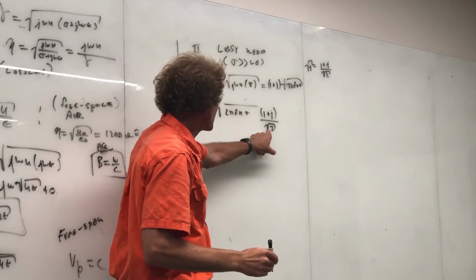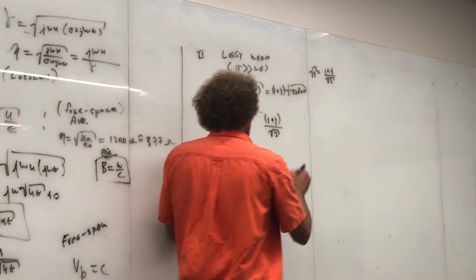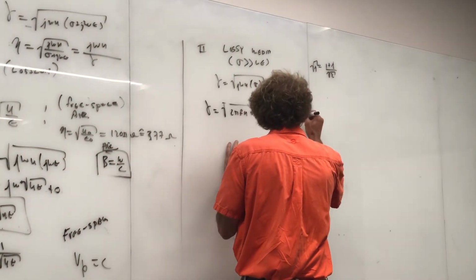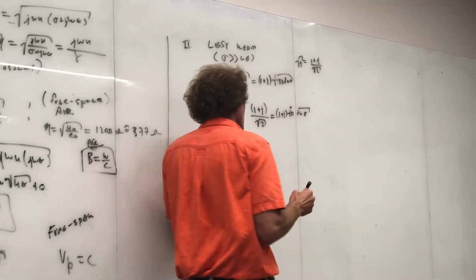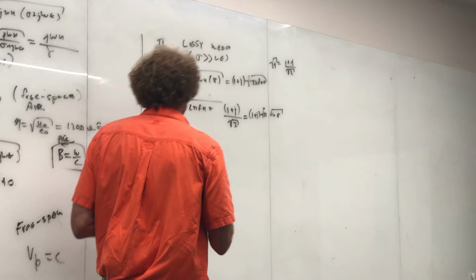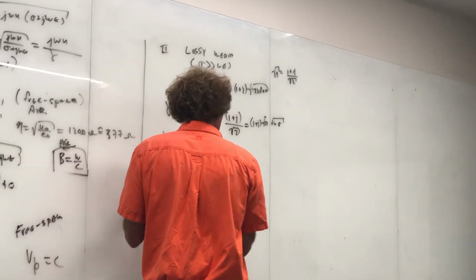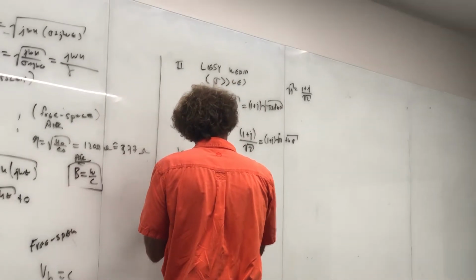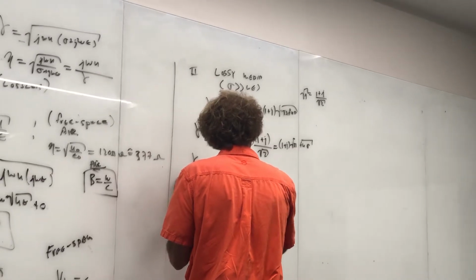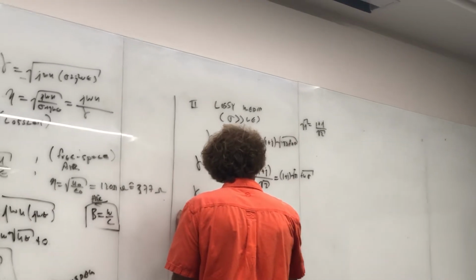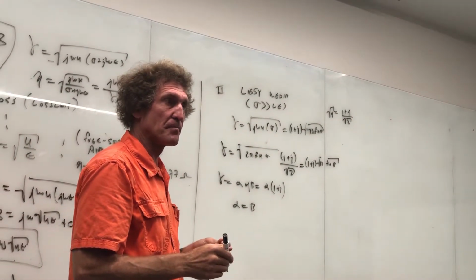And you can see I can take the square root of 2 inside this root symbol, and so it's 2 over 2, and therefore you will get 1 plus j times the square root of pi f mu sigma. It also means here that alpha plus j beta is really something where alpha is beta in magnitude. So you can just go ahead and put alpha or beta outside if you want, and just put 1 plus j here. Are you with me on this, class?